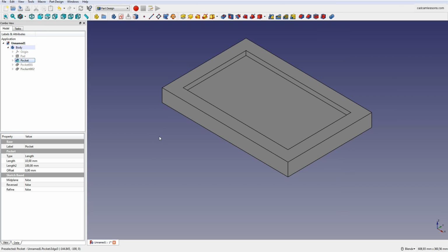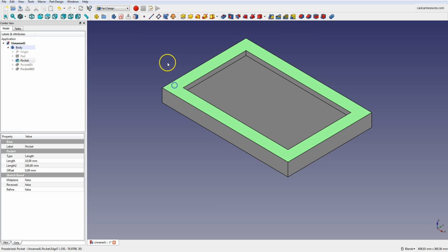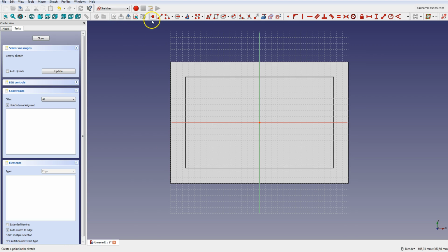OK, to use the create hole with the selected sketch, as the name suggests, we need a sketch. The easiest way is to add 4 points offset 12 mm from edges, but the points themselves are not enough, but about that in a moment. Let's add a new sketch. OK, add 4 points. OK, let's add some constraints. Horizontal for these points and vertical for this and these points.